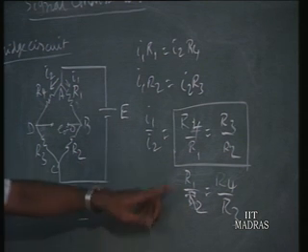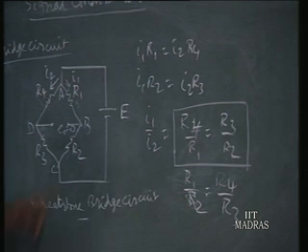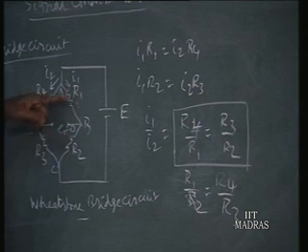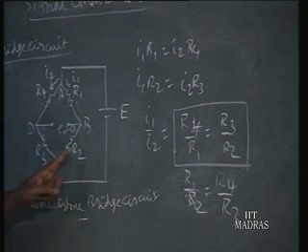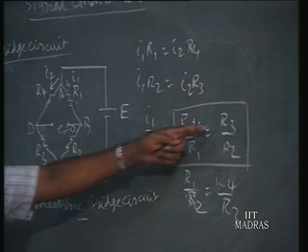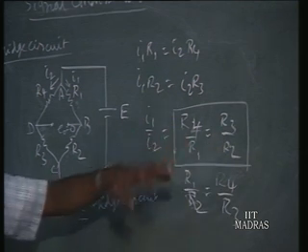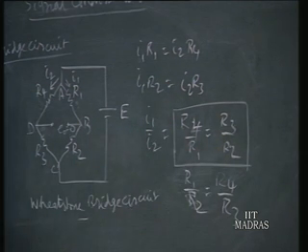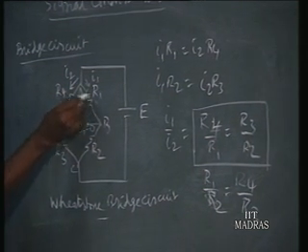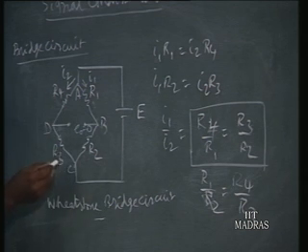the ratio of adjacent terms R1 by R2 is equal to R4 by R3. So, again go to the same side, write this equation, or you can write R1 by R4 is equal to R2 by R3, or R4 by R3 is equal to R1 by R2. That is, R1 by R4 is equal to R2 by R3. Anyway you can write, but what has to be remembered is the side from where you start. For the other ratio you go to the same side. If we start with R1 by R2, then write R4 by R3, never write R3 by R4. That is the only way to remember it.